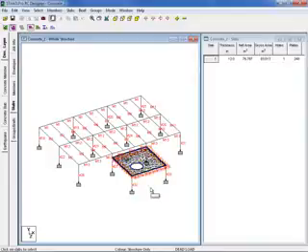Now, a typical workflow once we get into the RC Designer would be to start at the top of this Page Control area and work our way down. So our load envelopes have been created, physical members have been created, and also our slab objects. We are now ready to move on to the next phase, which will be designing concrete beams, columns, and slabs.